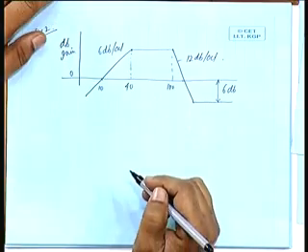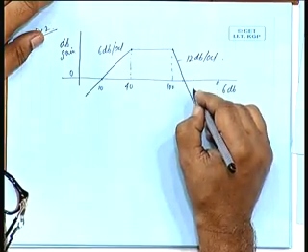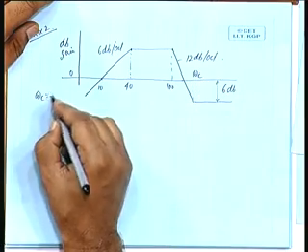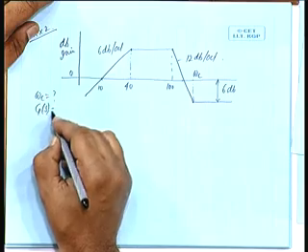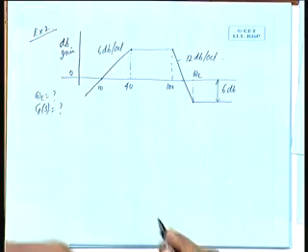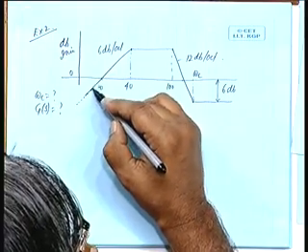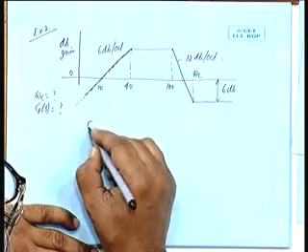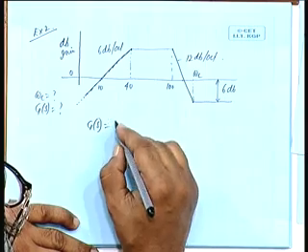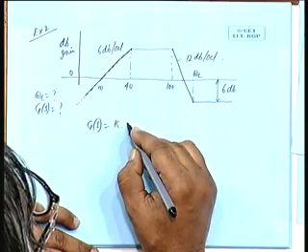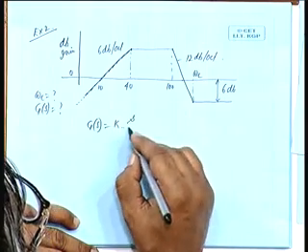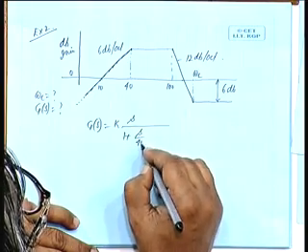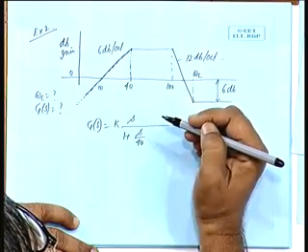What would be, once again, what would be Gs and this frequency omega c and Gs. So, this is going at a slope of 6 dB per octave. So, what could be the structure? K into S in the numerator, then 1 plus S by 40, okay.